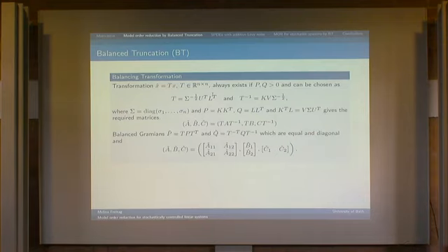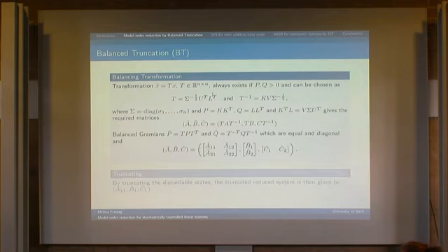Okay, so you've done this transformation, and you haven't actually done anything with the system apart from a basis transformation. It's just a basis transformation of your system. So you have a balanced system, and what you do is discard the states which have small singular values. Because now in your transformed system, your reachable and your observable states are the same. You neglect all the states that are not easily reachable, not easily observable, because they are not of interest, and so you do your truncation. So you balance the system, and the next thing you do is your truncation.